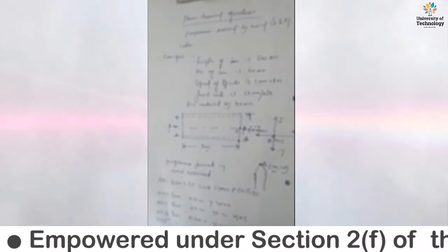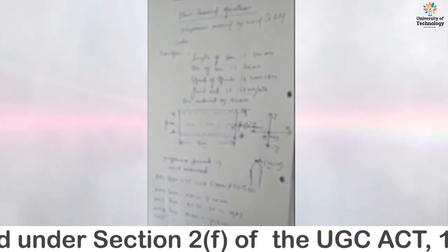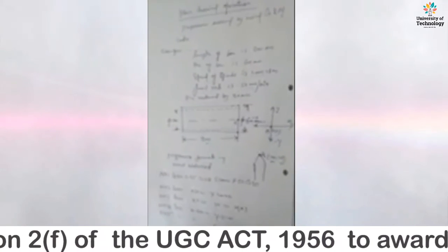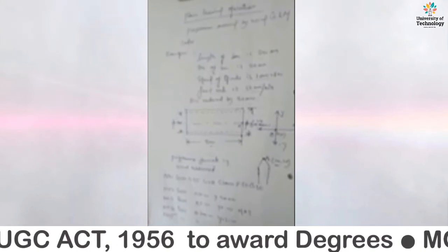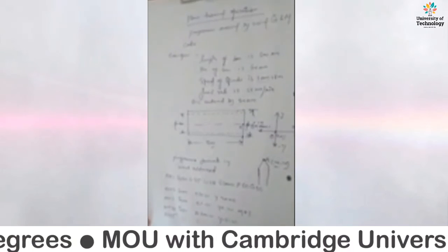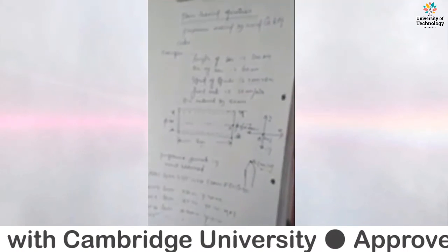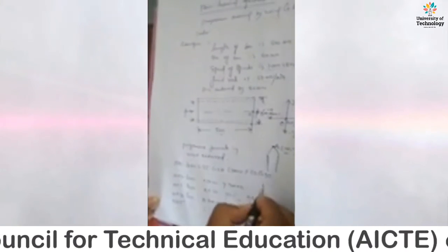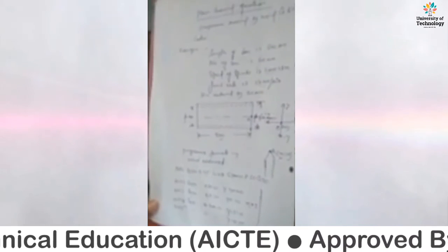also G01, and that is a fixed movement, and in Y we want to reduce the dia of the particular bar by 20 mm, then we can repeat 10 times the minus 2, and so on up to Y minus 10. So we can reduce the particular dia by 20 mm.